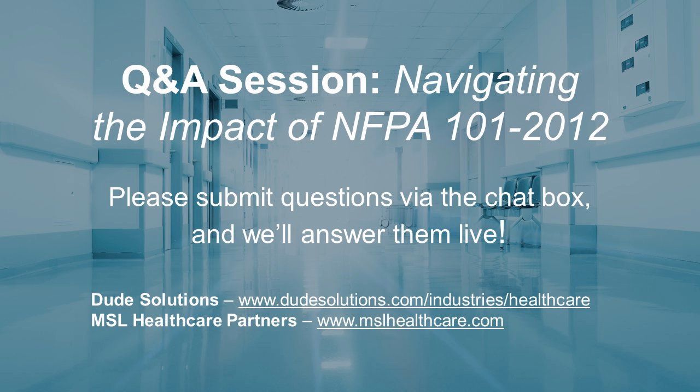As a matter of fact, there are some states that are saying that any rated door must be inspected, whether or not that door is required. I was at a hospital recently where the door to the engineer's office, because they renovated the engineering department some time back, they put a 90-minute rated door in his office. No reason to have it there, but there are some states that are saying that because that 90-minute door is on his office, it must have all the requirements that a 90-minute door would require, even though it's in a non-rated wall. So how this is going to play out across the country is going to be interesting to see. But basically, it is a much different inspection, this fire door inspection.